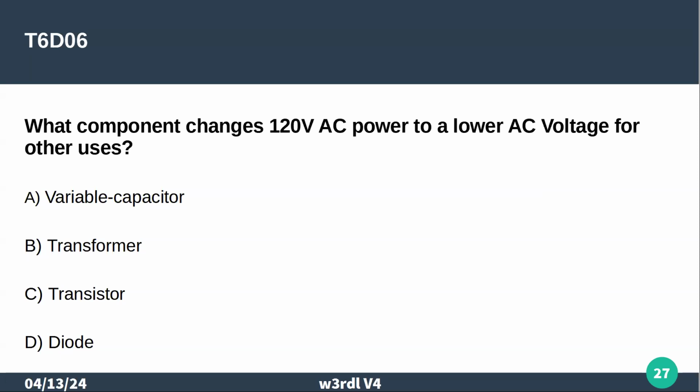You'll see it a lot in audio. PA systems will use isolation transformers for that very purpose, to prevent ground loops and hum coming through the speaker. Really? Huh. See it in quite a few cases. Interesting. Okay, I got the idea.